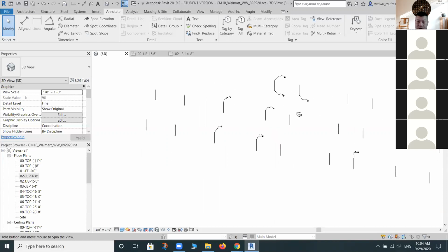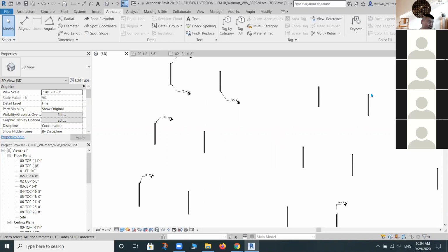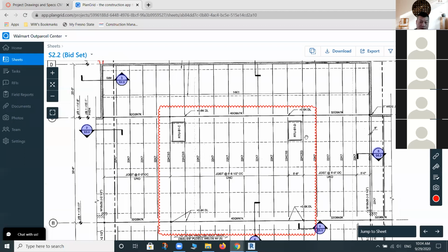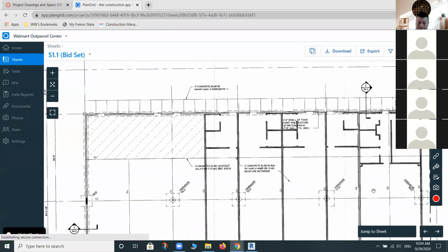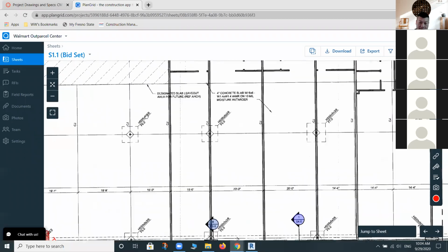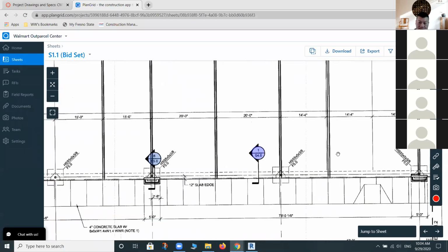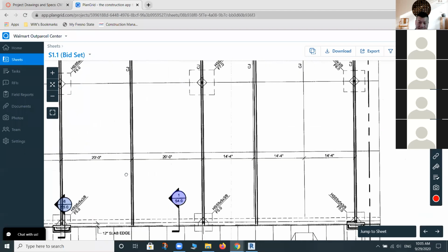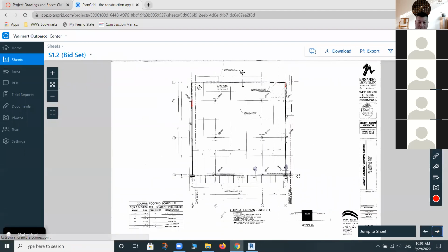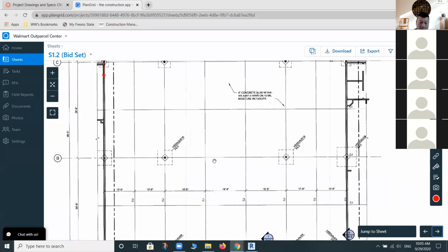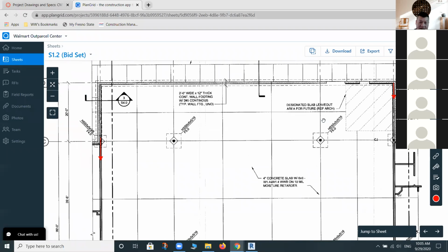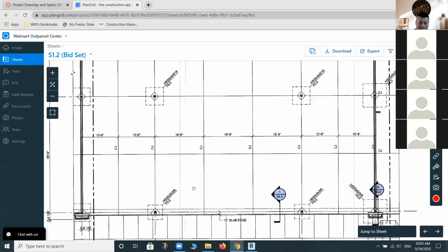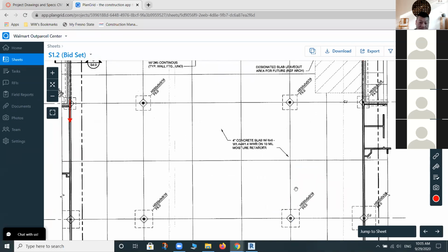So that kind of concludes our columns. But that's not done yet. Everything hasn't been finished yet, because why? Well, if you look at your drawings and go back to S1.1, you realize some of the columns are 3/8. I would say the majority of columns in Unit A are all 3/8. The ones which are not 3/8 are in the middle. In Unit B, you'll see most of those columns are 5/16. So you need to change the ones in the middle, those 4, 1, 2, 3, 4, to be 5/16.